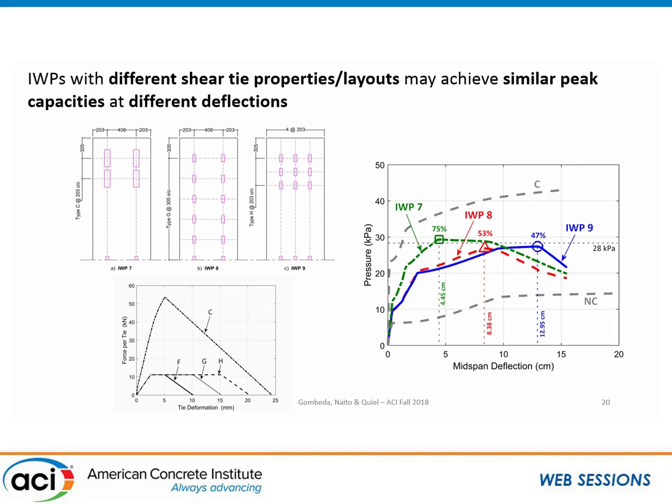the ties. And it doesn't have to be only the properties of the ties. You know, Marlon had talked about ductile and brittle, but it's also the placement of the ties. Because in reality, the slip is larger towards the end just based on curvature and how the panel behaves. So there's that to consider as well, which is why the model incorporates both of these.